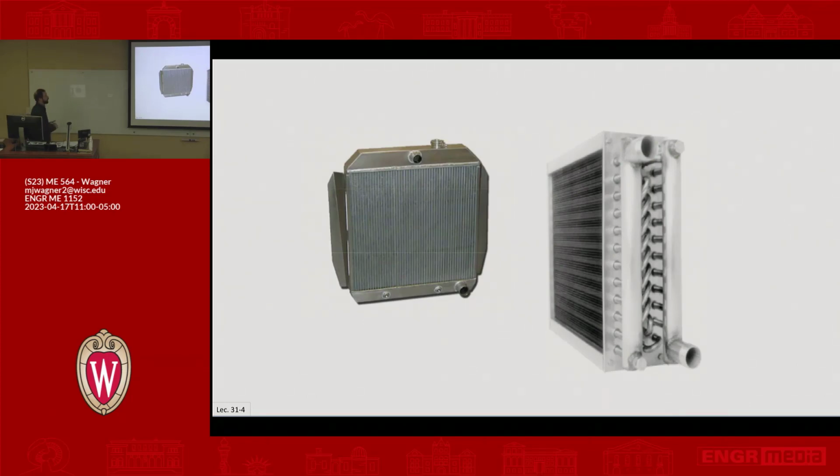So these are really common. If you go look at your air conditioner or the unit inside your furnace, it's going to look something like this. This is a cross-flow heat exchanger where you have the refrigerant or whatever it is going through these tubes, contained at high pressure. Then you have air that's forced across. So that configuration of having not counterflow and not parallel flow, but actually flow that's coming across, has a different thermal performance, which we'll talk about on the next slide.